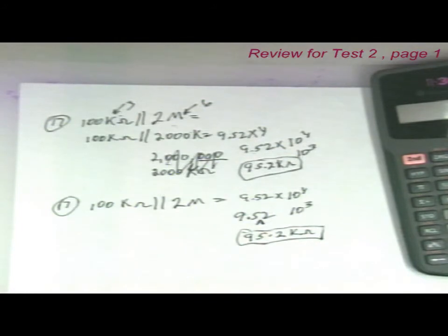If you measure a lower than normal total current in a parallel circuit, what does that tell you? Now let's think. Think back to what I just said. If you remove a resistor, the current is going to decrease.